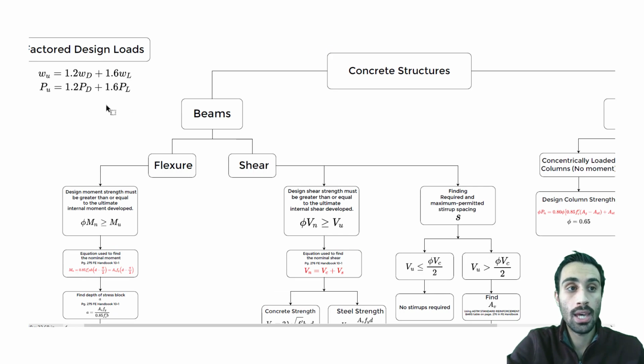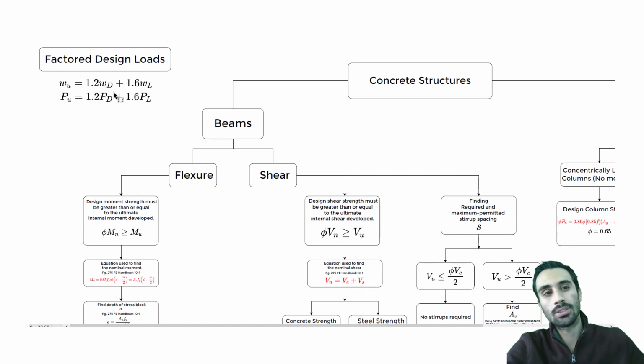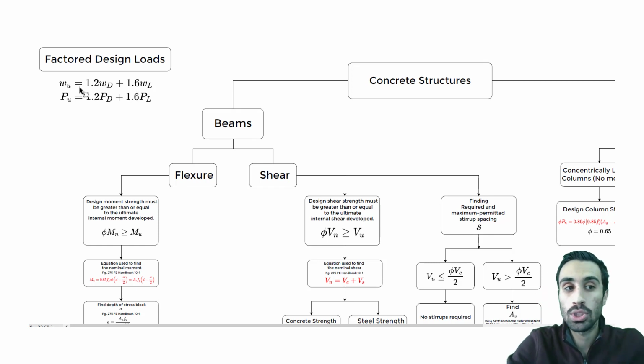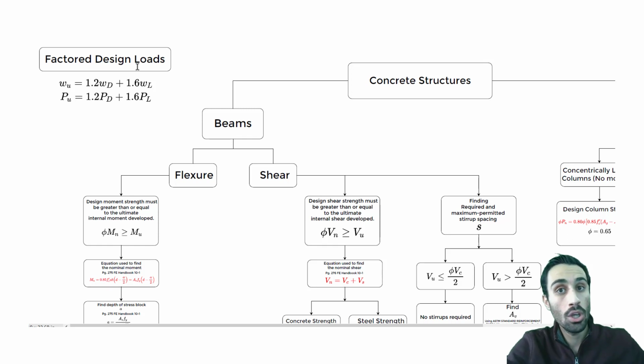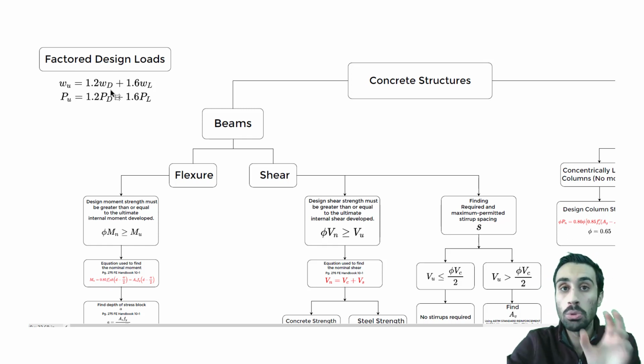And I just want to note that for the factored design loads, I just put that there because many of us tend to forget this, but if you do a lot of these examples, you'll probably have these memorized. The factored design loads is what we always use. Although we're not using it here, make sure you know this and always use the factored design loads in your analysis. Always, analysis or design.